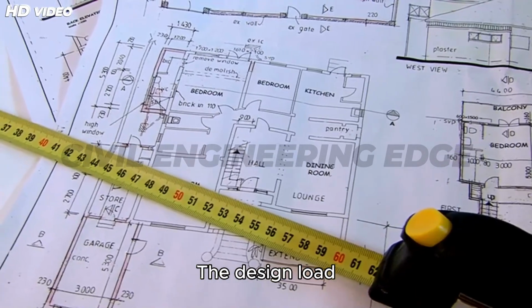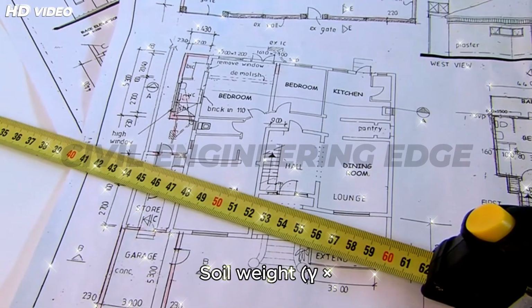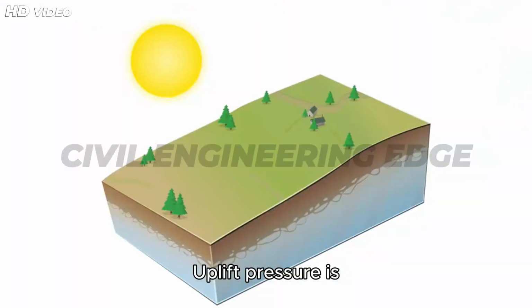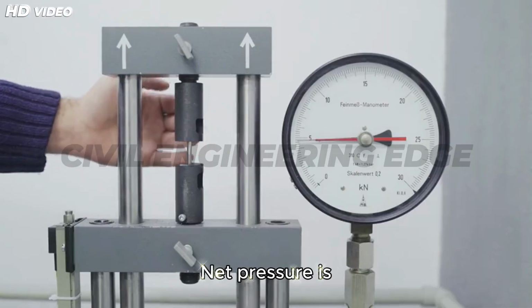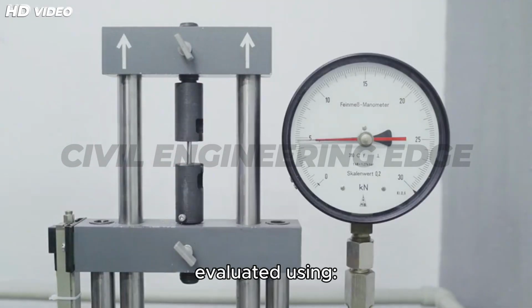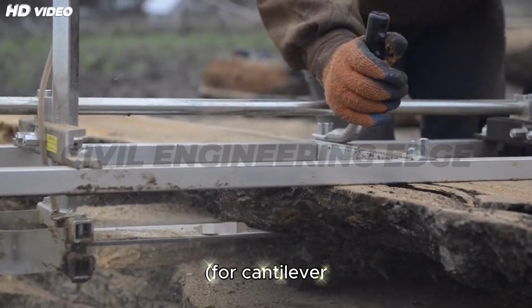The design load includes self-weight of the slab, soil weight (gamma times thickness of backfill), and surcharge load if applicable. Uplift pressure is considered from the soil bearing capacity and groundwater if present. Net pressure is calculated, and the maximum moment M is evaluated using M equals W times L squared by 2 for a cantilever slab. Here, W equals net load and L equals heel projection.